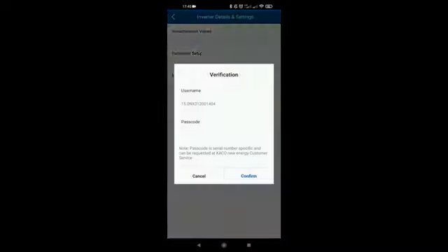And there we can see, here we have the parameter setup. It's really important to know at the first time we can read the parameters without a password, but if you change anything and confirm it, you will need the password at the next time. We have no general password for this, so if you need this, you have to call our help desk. It's a serial number based password, so it's not the same for every inverter.